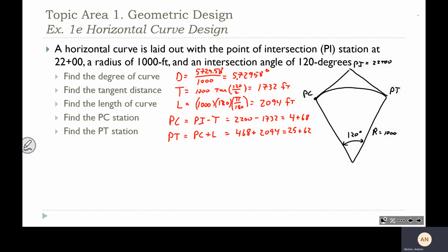So whenever you're designing a horizontal curve, the radius value is going to control how sharp the curve is. So we went through the stopping sight distance calculation yesterday, where think about a curve radius of infinity is essentially a straight line, and you're not going to have any problem seeing around the curve. That's going to be the most expensive to construct. And so you're always wanting to find the minimal curve radius, because that's what's going to allow you to fit the terrain if you're trying to kind of go between valleys and minimizing cut and fill for a construction project. So designing the curve radius is the next element.